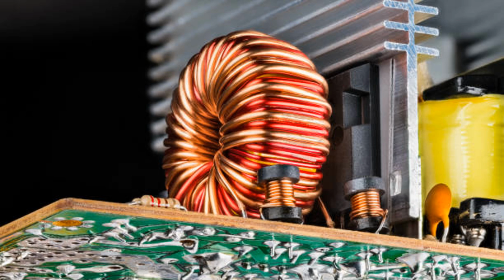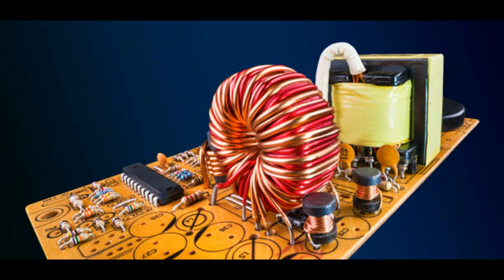2. How energy is stored. Inductance, L. The inductance of an inductor determines how effectively it can store energy. Inductance is influenced by factors such as the number of turns in the coil, the core material, e.g., ferrite, and the geometry of the coil. Current and magnetic field. As current flows through the inductor, the magnetic field builds up around the coil. The energy is stored in this magnetic field. The stronger the current and the higher the inductance, the more energy can be stored.